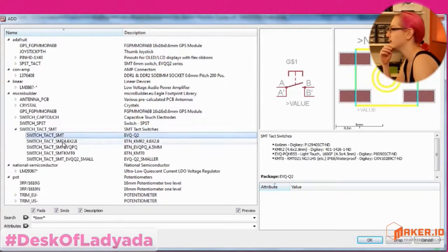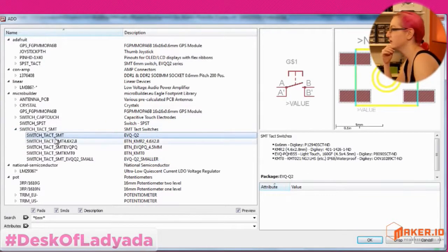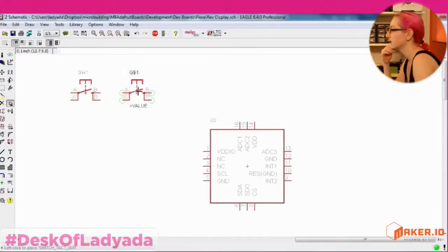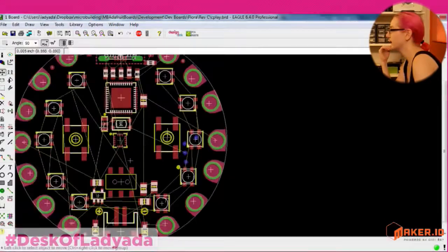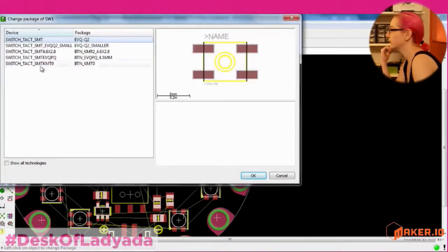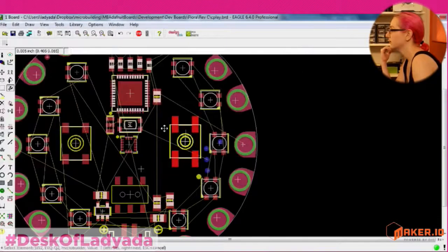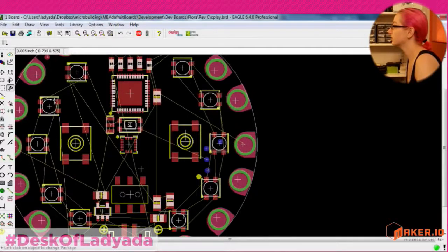Yeah, one of these. I usually use ones with really big pads. So I'll place these down here and then kind of show it off. But I actually don't need such gigantic pads. So I changed the package of these to be a little bit more compact, because it depends on whether the legs on the package of the button go out or not. Okay, so we've got 2 buttons. That's looking pretty good.